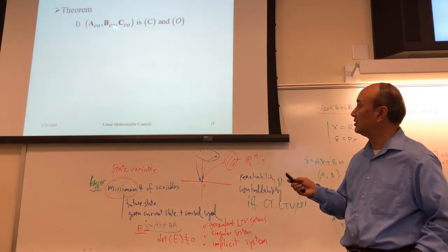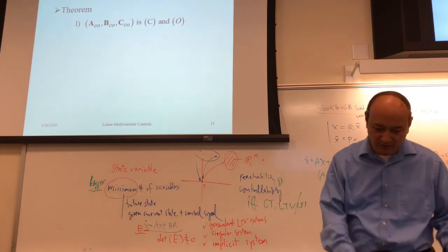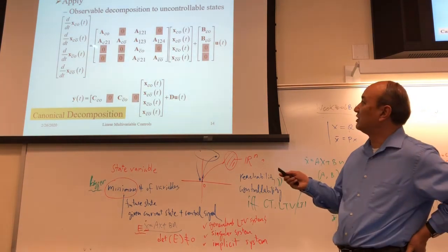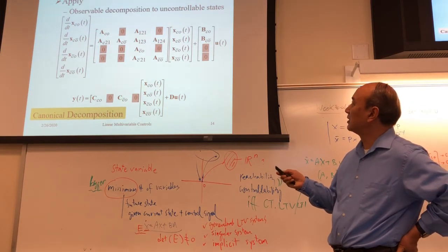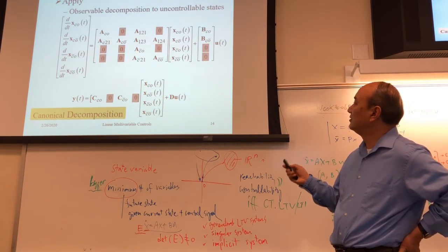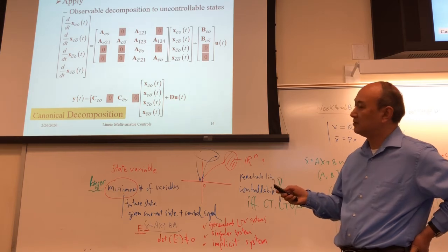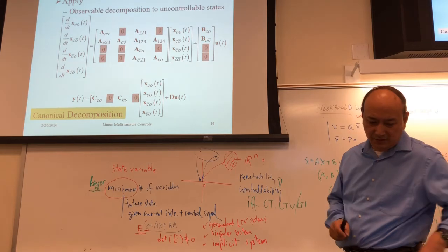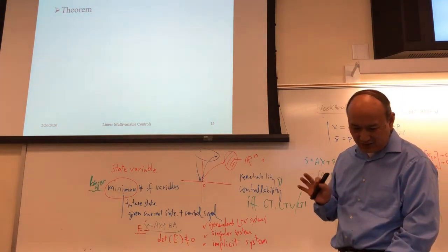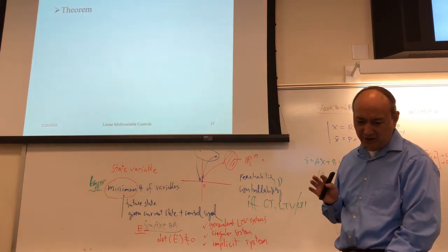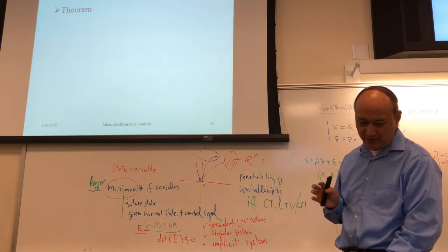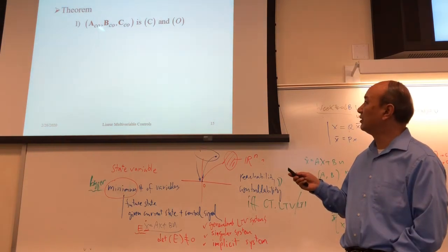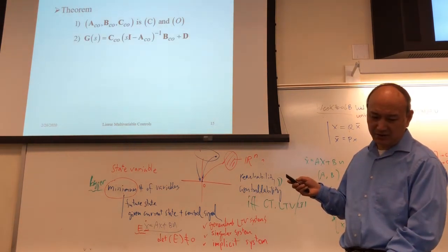Finally, you'll see what is really left that is both controllable and observable is this subspace: ACO, BCO, and CCO. I hope you can recognize where they are. These 3 matrices form the controllable and observable subspace, and the input-output relationship is only linked to these 3 matrices.